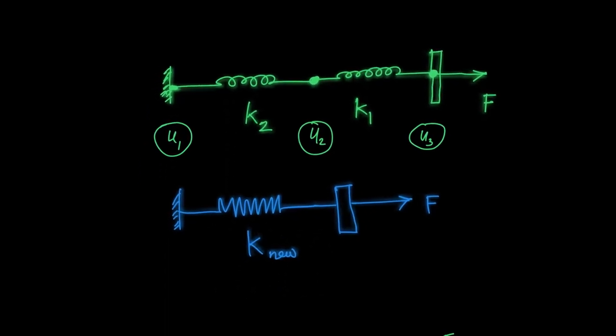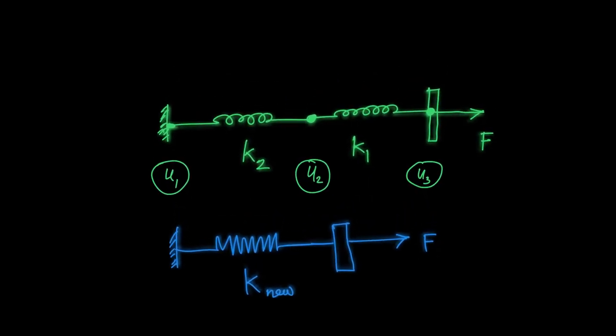The very basic concept of this arrangement is that when you have springs in series, the force acting in each of these springs will be the same. I hope you understood it. That's because whatever force I am applying here will be transferred to K1, and the same amount of force will be transferred to K2. That is the key takeaway you need to remember when you have springs in series.